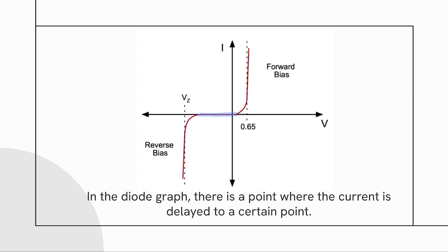In the part shown above in the diode voltage characteristic graph, we can assume that the current flows constantly because the slope of the current is very small. It is not perfectly constant, but almost constant. So, this state of small but constant flow is called saturation. So, you can think that it does not move.